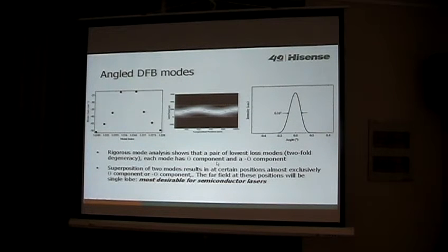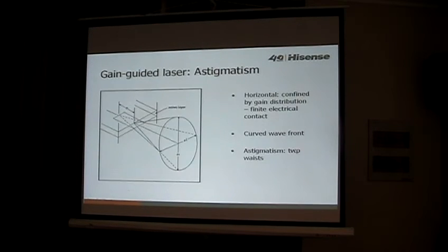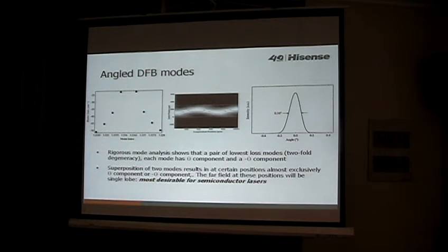What does it mean? In order to get a large power out of a semiconductor laser, what we got is a two-lobe beam, so the light beam propagates in two directions. If we only have one angle component, the output will be just along one direction. Also its mode distribution is very good, almost close to a Gaussian distribution. So this one probably has some promise to really reach high power semiconductor lasers.